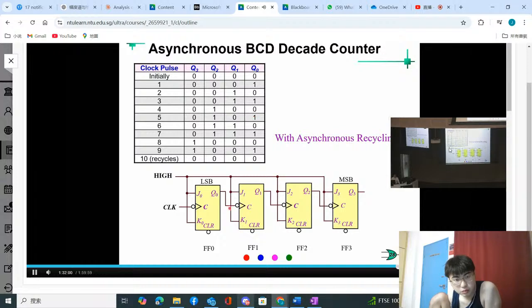To use an asynchronous circuit to design, we call it a ripple counter, which we learned before. I use a positive clock edge, but I take from Q0 bar, remember? It will generate a positive count-up counter. Now I use a negative clock edge. If I use a negative clock edge, then you will realize that I have to take from Q0.